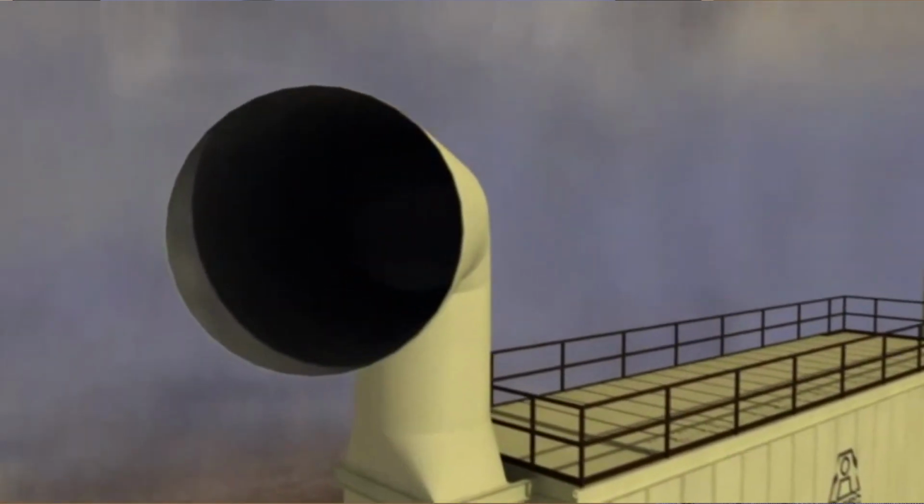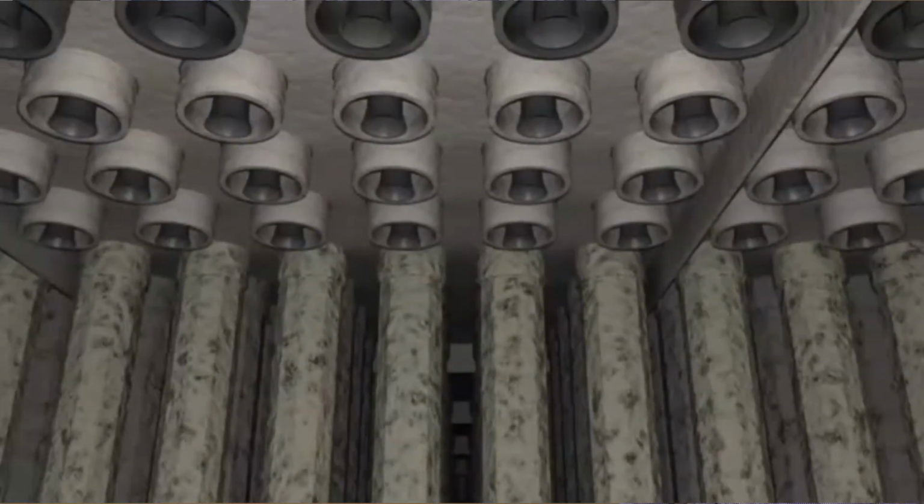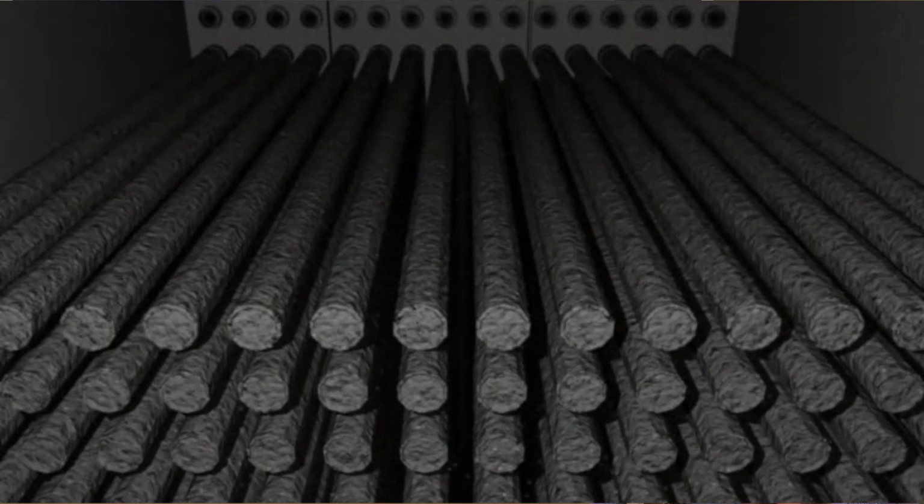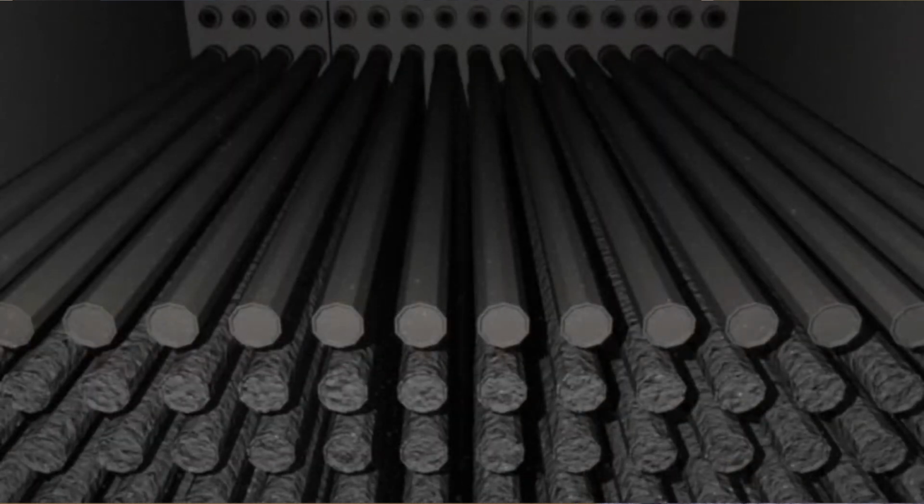As you pull the dust into the stack, it's going to fall down through. Here's your high velocity air. It hits the louvers, your minus 100s will fall, your minus 200s will move on into the baghouse. As the dust moves into the baghouse, it will collect on the bag. This is your dirty air side, and it will push the clean air up through the top to the clean air side. Here you see the blow pipes pulsing down into the bags, and what they're doing is shocking that bag and knocking that dust off. So here's an illustration to show that.